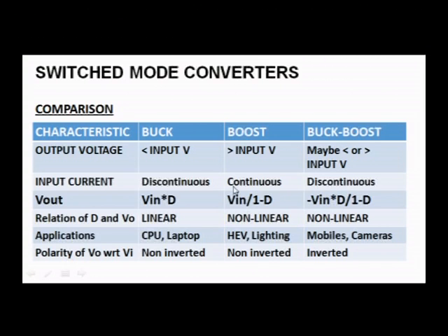But please see over here, input current means the inductor current. In the case of boost converter, the inductor is kept at the input. Immediately after the input voltage source, I have the inductor. So that is why the input current will be continuous in the boost converter.